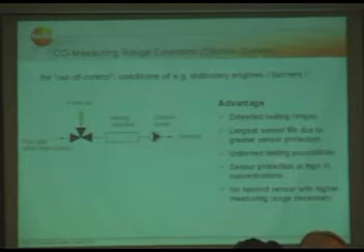And one thing has to be mentioned as well: electrochemical sensors have cross sensitivities, which are well known. Depending on which gas you are measuring and which gases are in the flue gas, some cross sensitivities can take place.